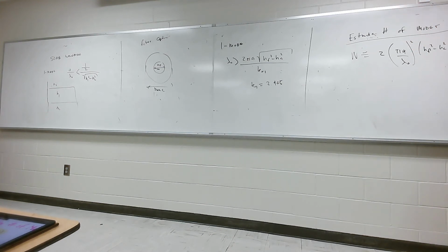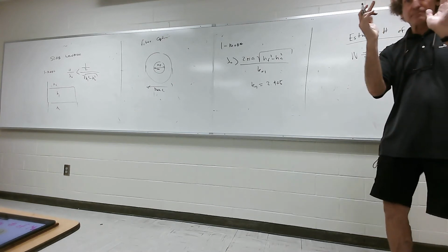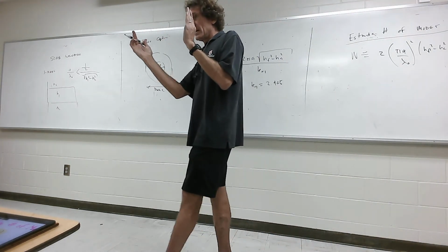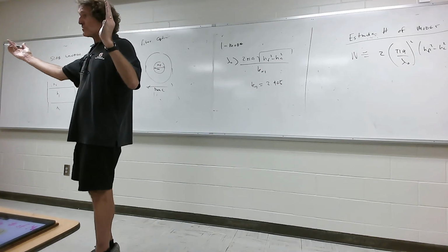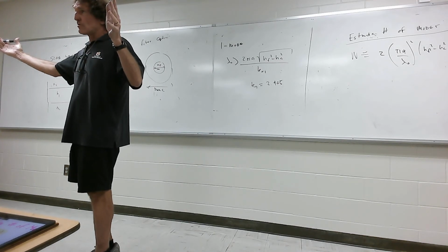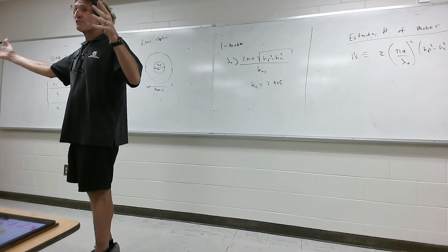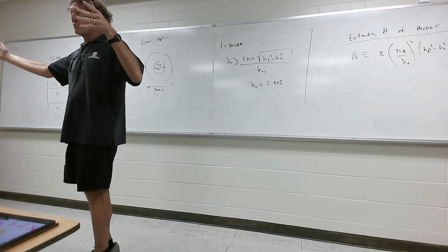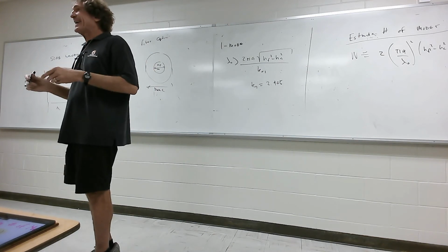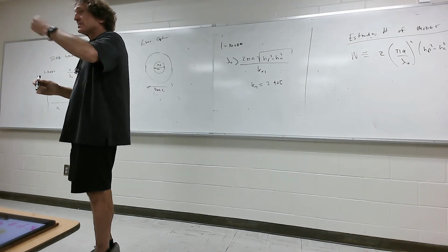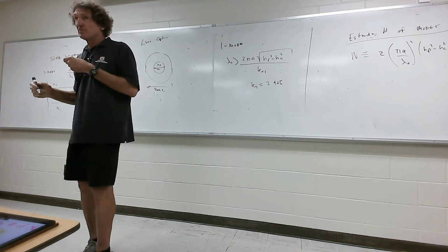So what they normally do is send a pulse. It's got a defined width. If you freeze time for a second and just look spatially, you'd see a whole bunch of photons from here to here and then none anywhere else. As that packet travels down, there's dispersion. The more modes, the more dispersion. All of a sudden the photons are over a larger and larger spatial region, if you freeze time. Well, pretty soon the first packet will broaden enough to be into the second packet, and you can't tell where the first packet was and the second packet started. And that's when you lose any kind of fidelity.